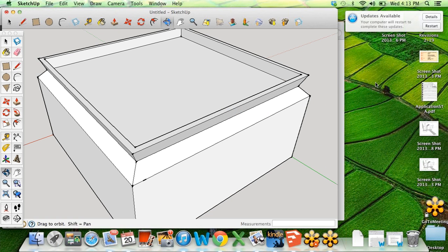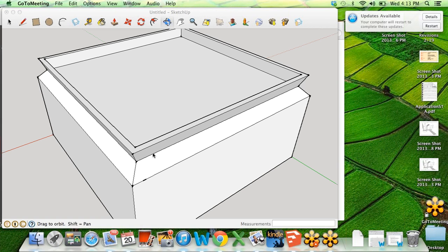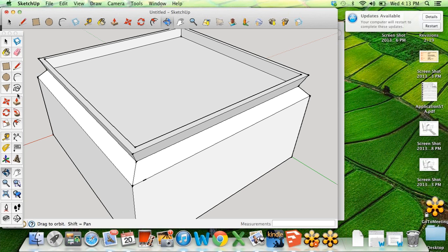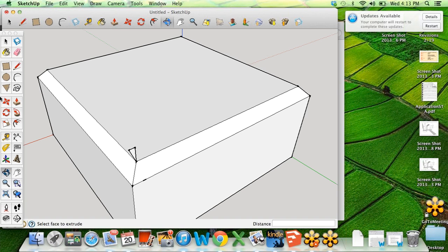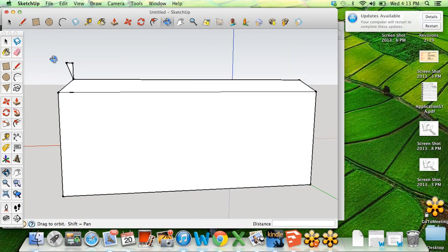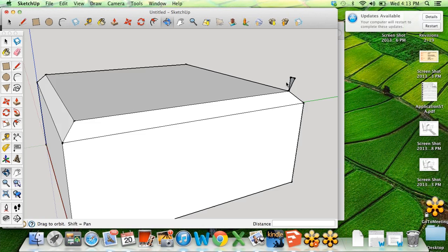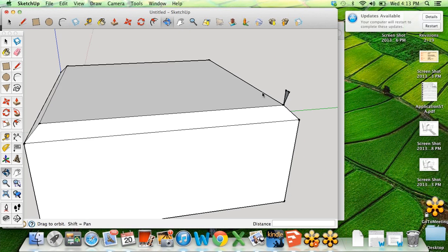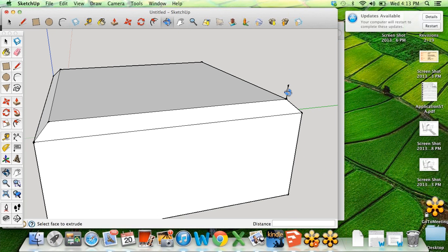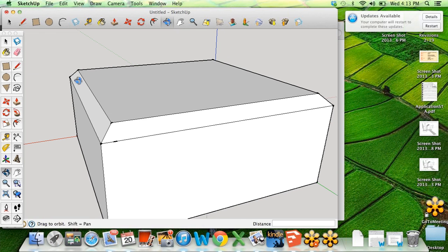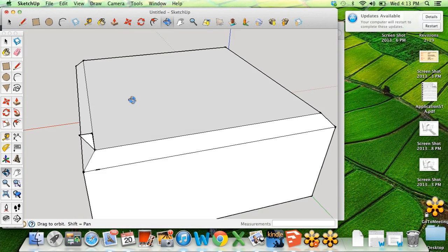All right, so now try adding something. And let me show you guys again how I added to the top with the Follow Me tool. I created this shape, this triangle on top of my building. I just drew it. I'll draw it again. Being really careful to pay attention to the axes I was parallel. First the blue, then the red, and then I connected them. Then I have this flat triangle.